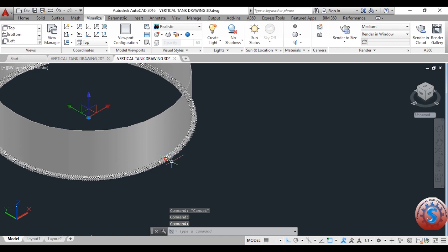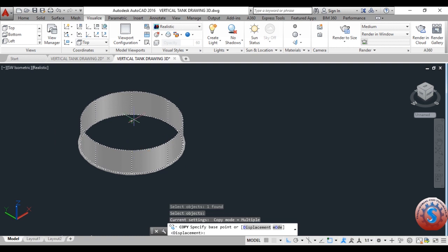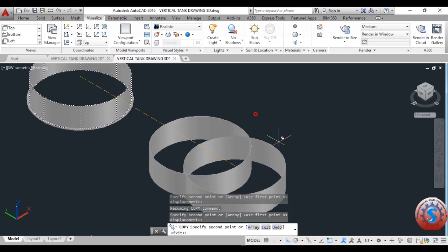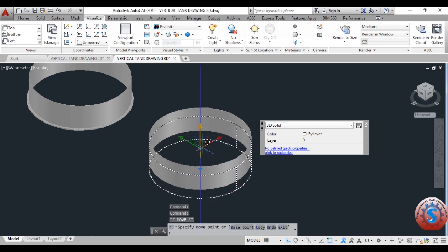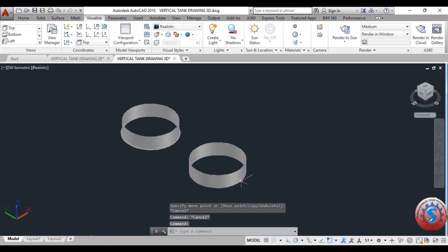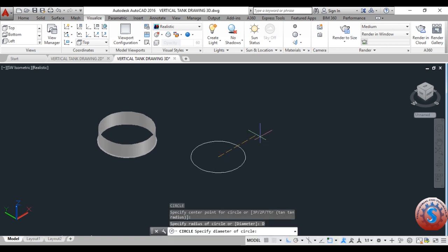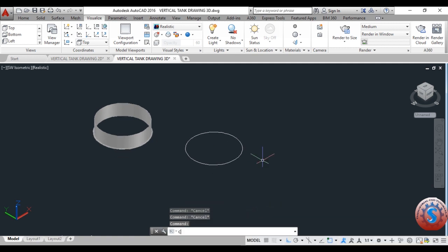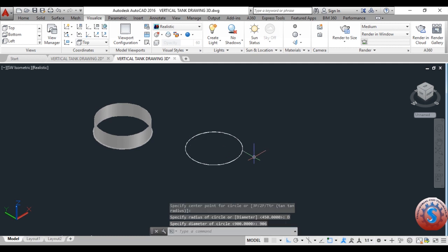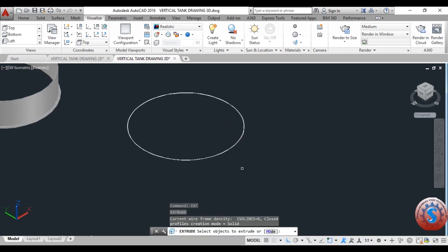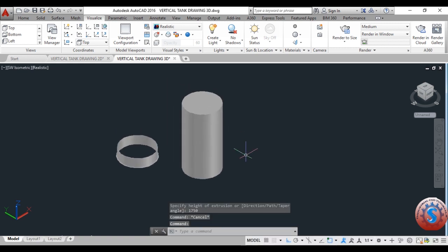You can also increase the height by using the model. I will show you. You can observe that I am copying the objects same as what I prepared before, and you can also extend this. I want to develop the model circle again, and the outer diameter of the circle is 906 and 900 is the internal diameter. You can observe 906 minus 900 gives 6, so at both ends of the 2D drawing you get the 3 mm thickness.